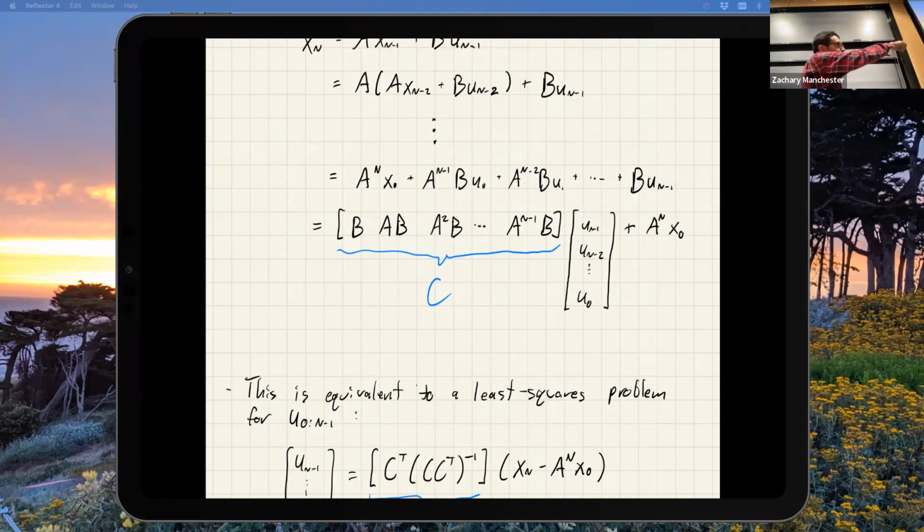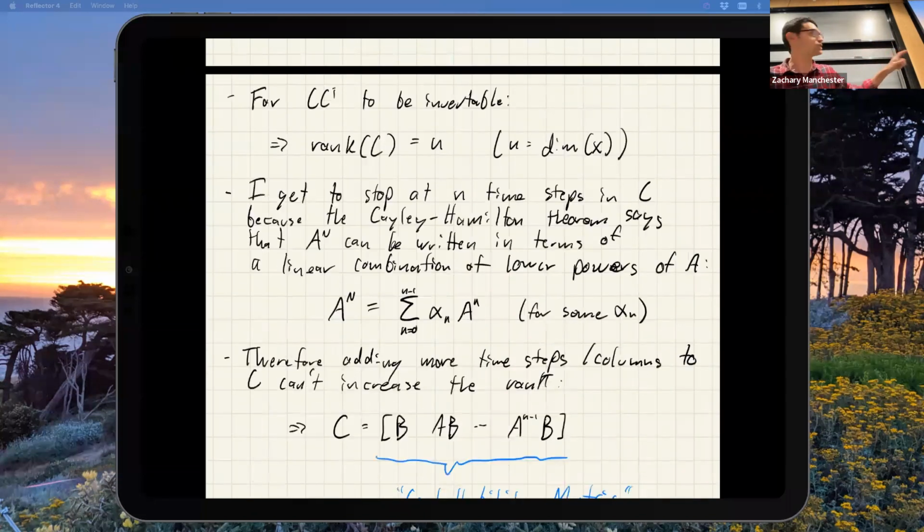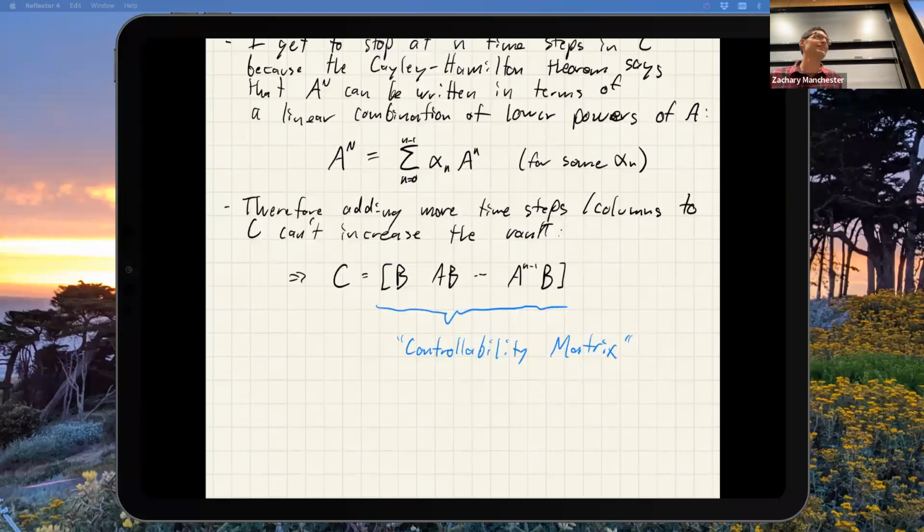When you raise matrices to large powers like that and then need to solve a linear system involving those high powers, really bad idea. So notice the QP version that we set up, that had no higher powers of A, right? Just A's and B's. So that's clean and nice. This has this bad conditioning thing, but this is the classic controllability result. This works fine if you're just checking this version down here in general, because it's small n, right?